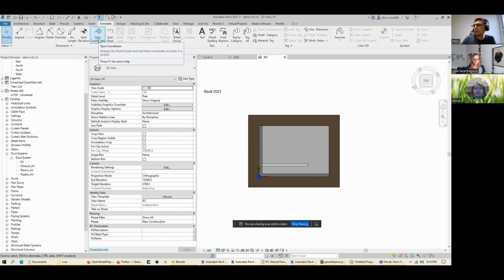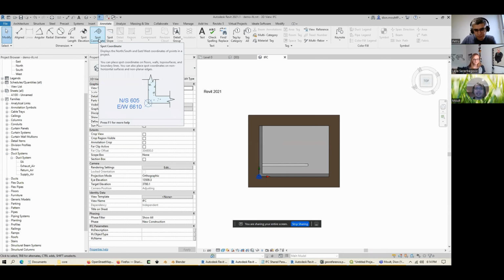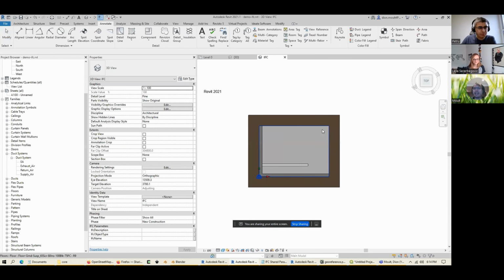And so they'll go around, on one hand, they'll have AutoCAD looking at things, and then the other hand, they'll have a spot coordinate tool, and they can come to very incorrect conclusions across a large site. And so it's always good, if they come away from this video saying, I didn't quite understand it, that's fine. As long as you get that it's a little trickier than it seems to be, there is actually a combined scale factor involved. Always ask the surveyor in doubt. If you're ever going to try and do any sanity checks as an architect, maybe it's a good idea to ring up the surveyor and share your screen while you're at it.